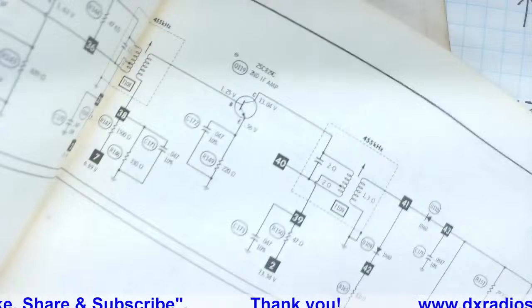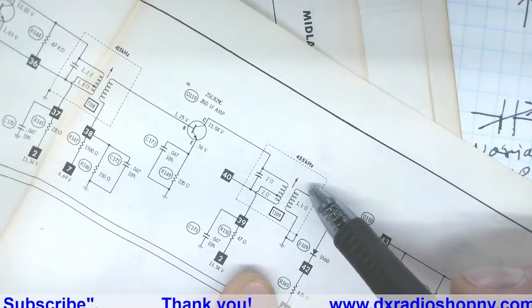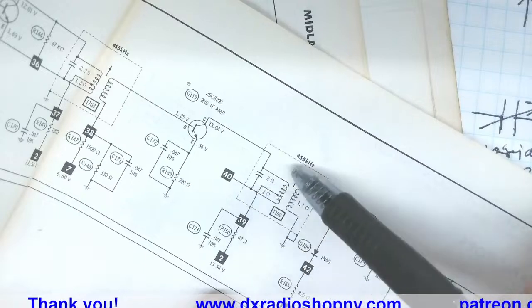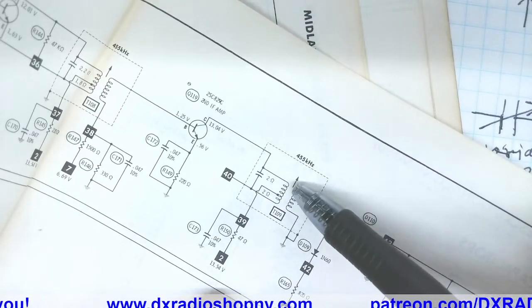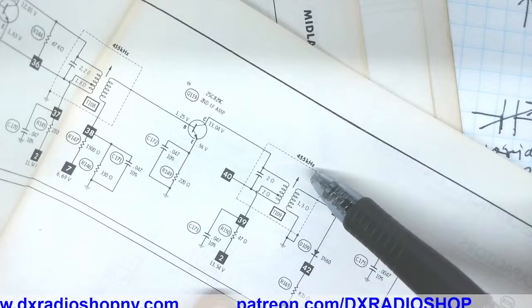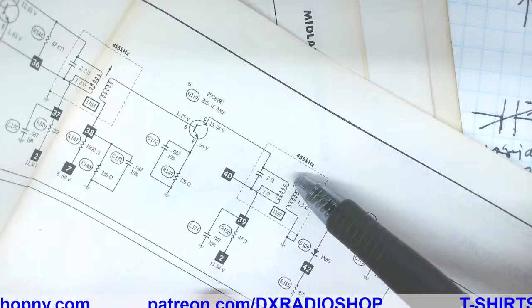So let's talk about that for a moment. Like right here's your tuning capacitance. Your 455 kilohertz. Well, that's a symbol for your tuning capacitance. These are those silver cans you find on the board. That's what's inside these silver cans. Now, some of them have a cap, and in this case does. Some of them do not. Some of them just have a standard coil on both sides to adjust the capacitance.